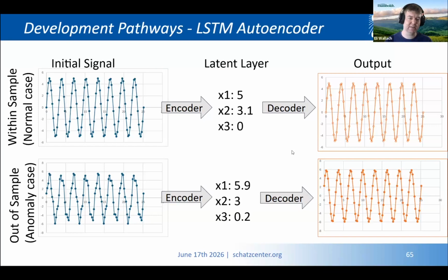We worked to train a long short-term memory autoencoder for detection of anomalies in the mooring line departure angle and platform locations. LSTM autoencoders are commonly used for this type of time series anomaly detection. But we found that it was difficult to train and it did not perform well. It's likely due to the chaotic and random nature of the system being responsive to stochastic wave and wind fields, where this approach would likely be better suited for a more controlled or regulated system. As such, there's no strong underlying relationship that we're trying to train the autoencoder.